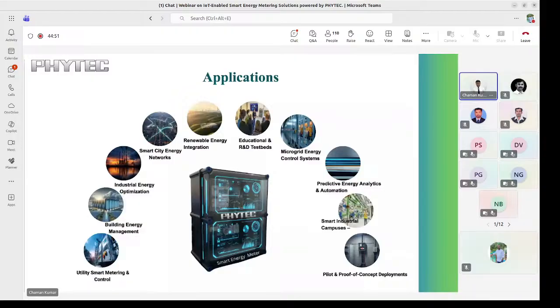I connect my DCU with this Ethernet cable so that it connects to the internet. If you want to see the logs, I will connect to this DCU. We are giving the supply to the DCU, and the NIC card will get the data. So now this smart energy meter is there, the load is there, and this NIC card is also available here. The meter will read the data, and the NIC card gets the data from the meter through UART.